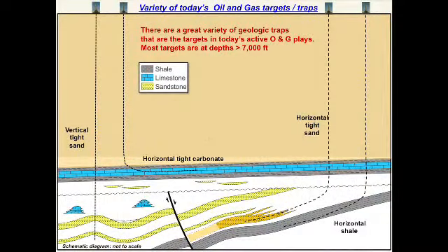First, single stage fracture stimulation, and later on in the 1990s we perfected technology that allowed us to do multiple fracture stimulations back to back in the same well, and then drill out plastic fracture plugs and allow for commingling of different reservoirs and simultaneous depletion of a number of different sands, or tight sands in this case, which really drove a huge revolution in tight sand development in the United States.